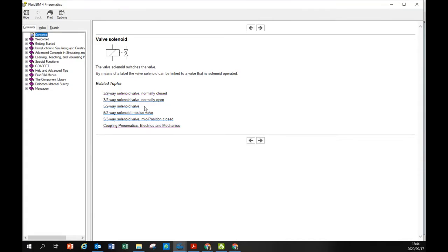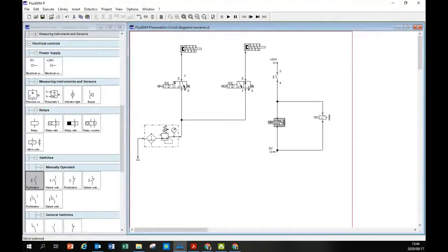They are both the 3-2-way valve, the 5-2-way valve, everything basically. So this is your gate to there. That's why they need to always be connected through the labeling because we can't physically go there. But with the real wiring, you are able to connect from there to there. That's why they say 1B1, 1B1 there, 1B2, 1B2 there.